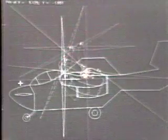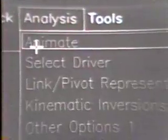The curves are calculated and displayed instantaneously, so as the designer moves his design positions around on the screen, the loci showing the possibilities for where pivots could be located track along and change their shape to reflect the instantaneously displayed design positions. This means that certain positions can be used to explore the possibilities for a design. They can be used as control positions. When the designer selects a link based on these Burmester curves, the designer can no longer put the pivots wherever he or she likes, but is instead constrained to position the pivots only on the Burmester curves.